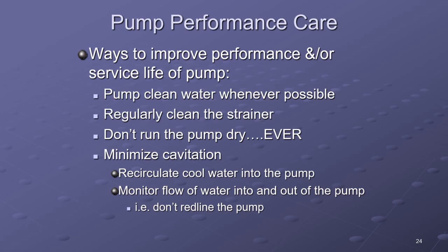There's a little bit of tolerance there. And I think saying don't run it dry ever, I mean, it's true. You don't want to run your pumps dry. But at the same time, if I'm getting water up to it and it's turning, that's not necessarily a problem. There's a balance. The key is that you can get them hot, and if they get hot, you can start breaking things like mechanical pump seals. So however you need to do it to take care of your mechanical pump seals and the equipment in there, if that means make sure that there's water sitting in it when you fire it up, great, because water absorbs a lot of heat energy.